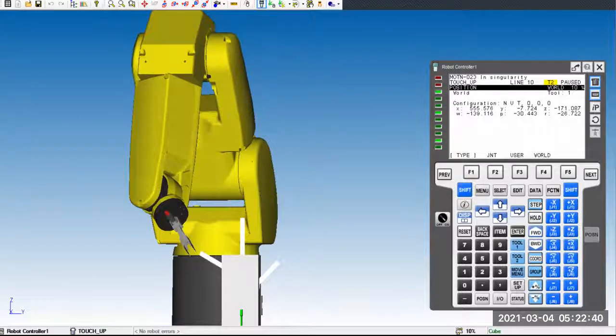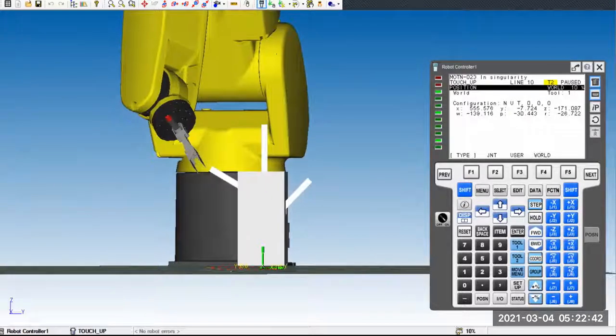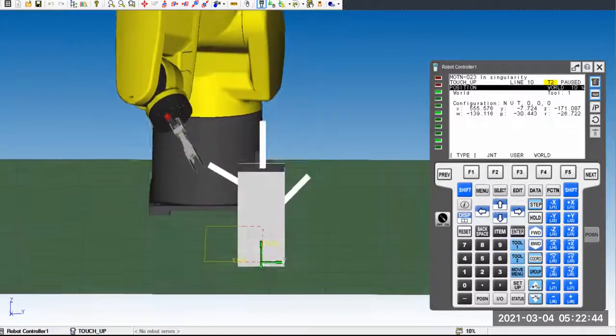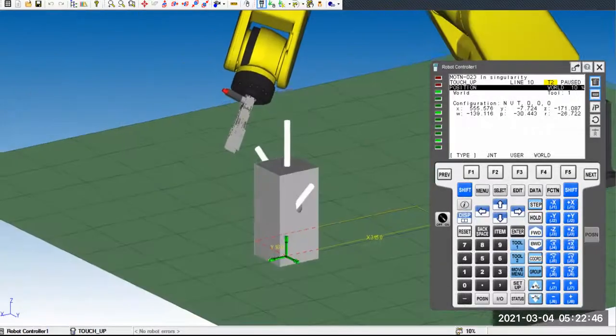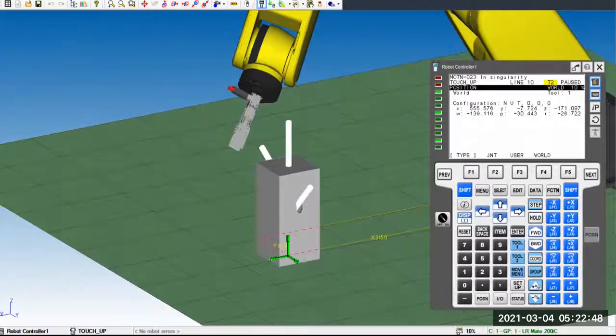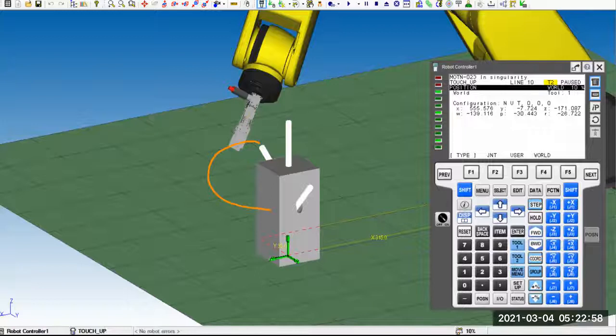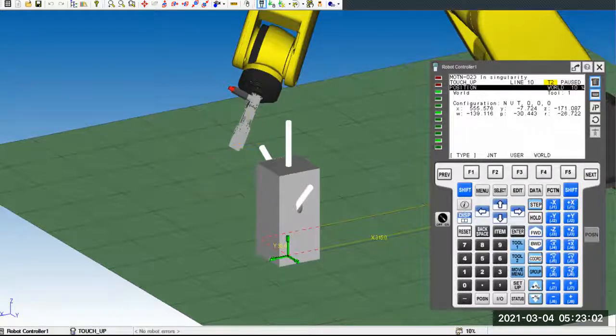Okay, so if you look at here, the gripper sort of lines up, right? If you look at, no, not good, right? So we have to rotate. In this angle, maybe we should, not maybe, we should rotate around Z, right? Positive rotation direction. If you understand the second right hand rule, you can apply it here.